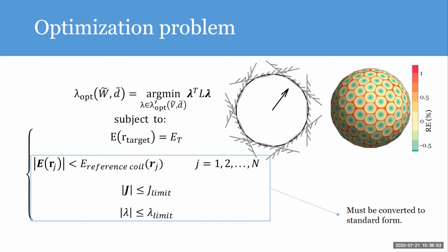So if we return to this again, if we had trivially canonicalized the problem here into the canonical form that Rasmus showed us, where each of these is turned into 16 for 2D because it's 2D constraints, and these are turned into 2 constraints, and these are turned into 16 per field point, the problem will be too numerically difficult for any of the commercial solvers I have tried to even find a feasible solution because of numerical problems, despite my perfectly well knowing that that problem would have a solution, because even if I would constrain it looser than that, those constraints would never be triggered by the solver without them existing.